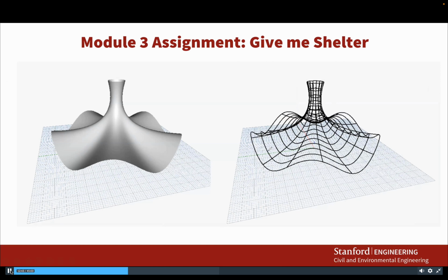Adaptive components by points would require, for the longitudinal beams in this case, a point here, a point, so our second radius circle was around here, and our third would be here. These 3 points would be just enough to create this shape in the Revit environment.